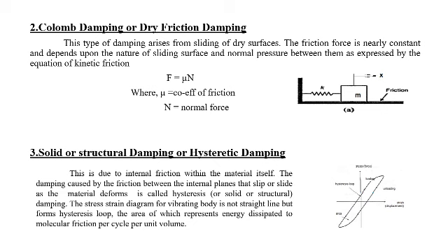Last, the fifth type is magnetic damping, a phenomenon that has been observed for many years, by which vibrating, oscillating or rotating conductors are slowly brought to rest in the presence of a magnetic field. In magnetic damping, there is damping due to eddy currents set up by the movement of the system in the magnetic field. There is a resistance to the vibration due to the eddy current set up in the magnetic field. This is the last type, magnetic damping.